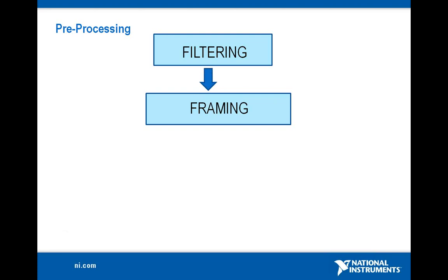In framing, framing is used to detect the dynamic changes in the speech signal. It is necessary to analyze the signal in short intervals. So we divide the waveform into small frames of 15 to 30 milliseconds each, and these frames are put into analysis separately.